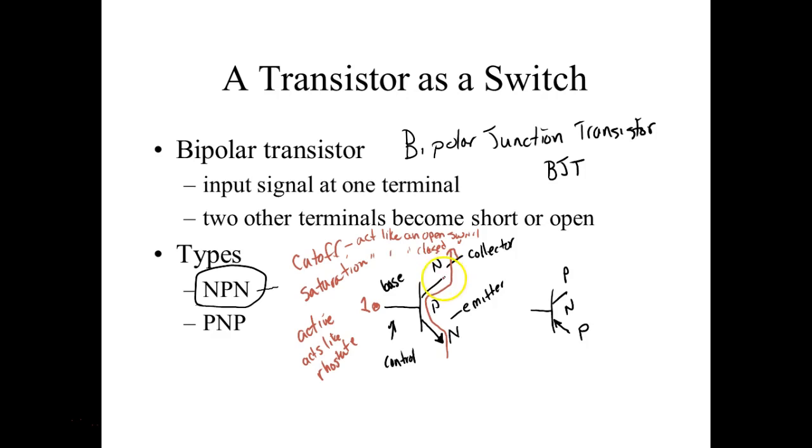So we're not going to take this guy and hook it directly to a plus voltage, because when it turns wide open we'd have a short circuit. So we got to have some type of load in the circuit, just like a switch. A switch controls the load, right? I'm not going to take a switch and put it between my 2 lines. I'm not going to do this, even though some people do this on motor control. Because if I close that switch, I have a short circuit. So we're always going to have some type of load right there.